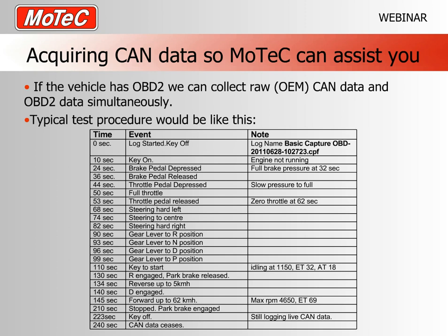Now when you press the brake pedal, there may just be a switch or there may be a brake pressure sensor, and so this is how we know when we look at this data log, we can tell from these timestamps just when various things happen. So you can see it's not a terribly complex process. Generally it only takes a few minutes of testing on the vehicle.